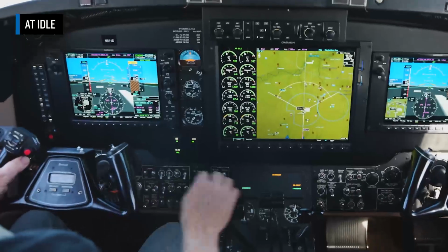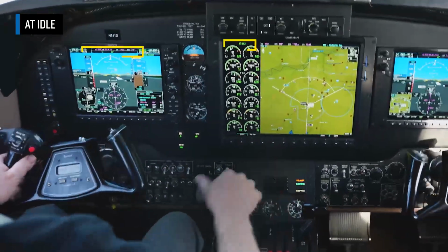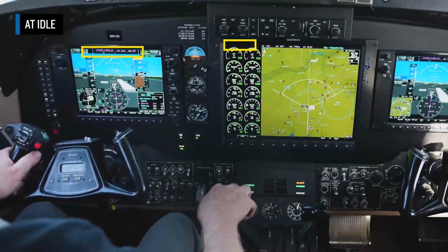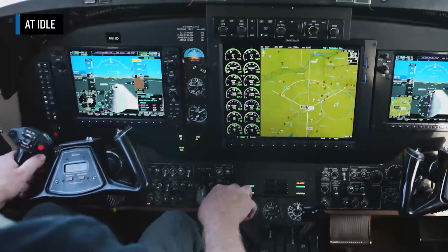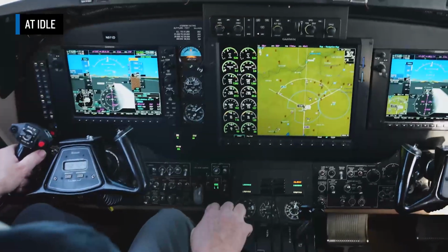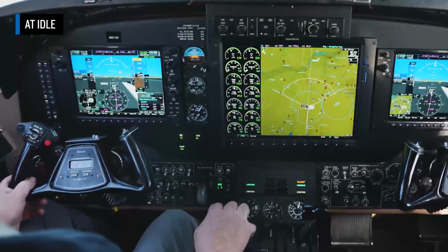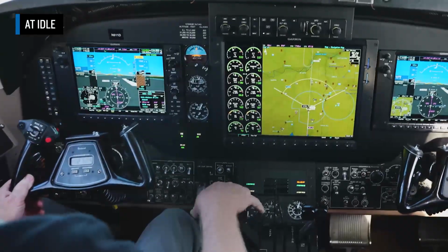About 2 to 5 seconds after touchdown, the autothrottle will disconnect with no alerting indications. If the system does not detect the airplane is on the ground within 20 seconds, the autothrottle will disconnect and alert the pilot. This concludes video 4 of the King Air B300 Autothrottle series.